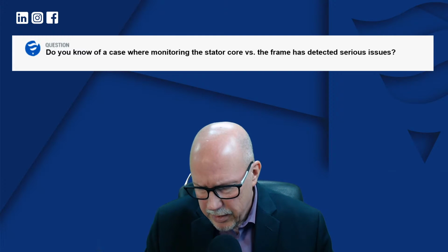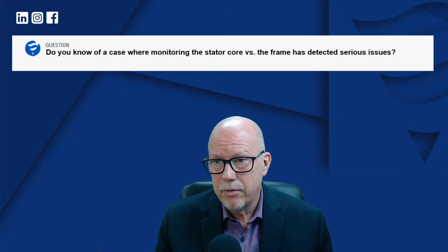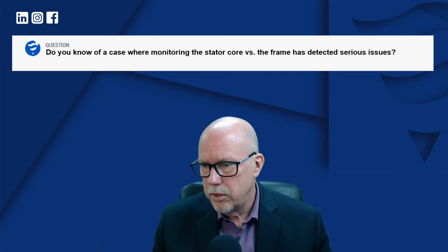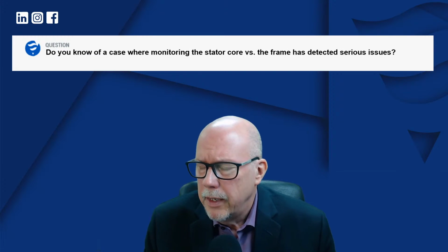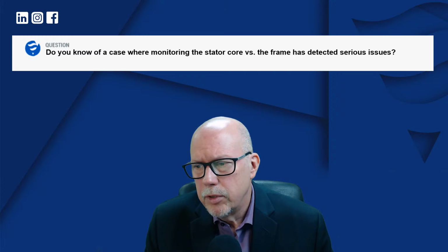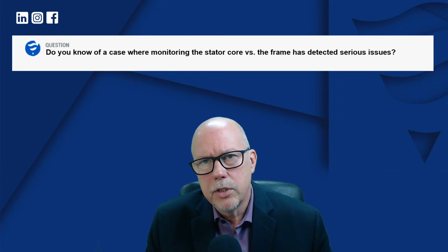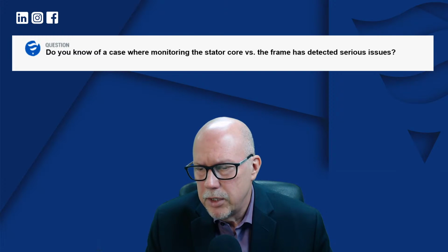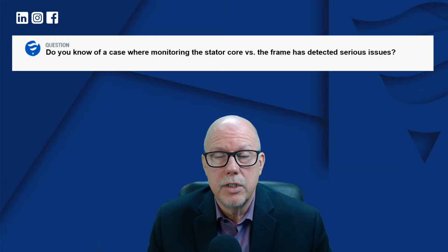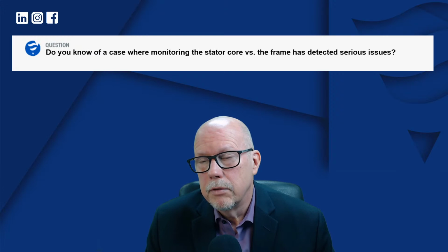We also had a case in the United States. Unfortunately, it was after the fact. They had issues on their units, and we installed end winding vibration and some stator core and stator frame vibration sensors. And we did a whole bunch of testing. And by the time the information was sent back to us, one of the machines failed. And it was a stator frame failure.